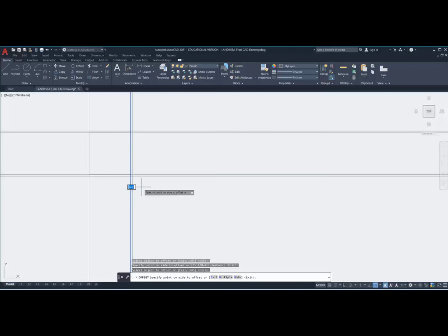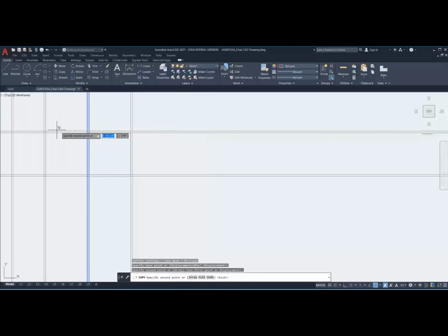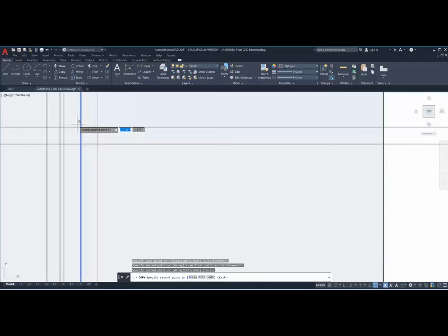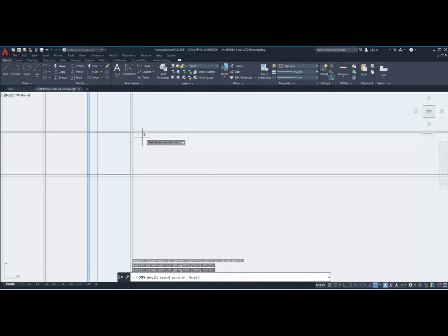And I'm going to offset this grid in both directions, horizontally and vertically, on all four sides of this 6 inch by 6 inch square, and then I'm going to duplicate this. So I've selected the two lines, and I'm going to copy and paste it just like we had before, but I'm going to pick a base point at the opposite side of the 6x6, so then I can just click on the different points and make sure that I'm selecting the same point.